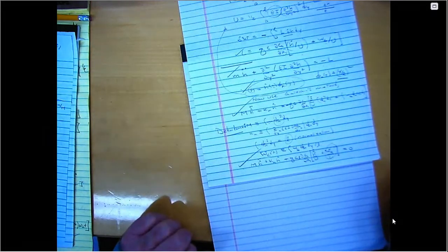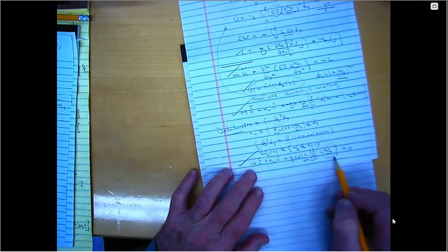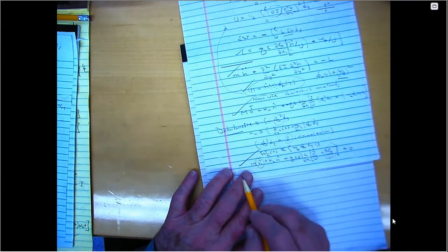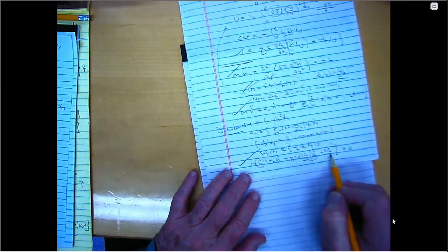Okay? You still with me? So, all we have is a spring mass damper system with a forcing function from the gust. We want to find out how does this thing respond in time. We want to find out how does H change with time given a gust input.